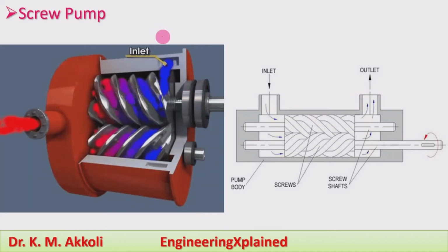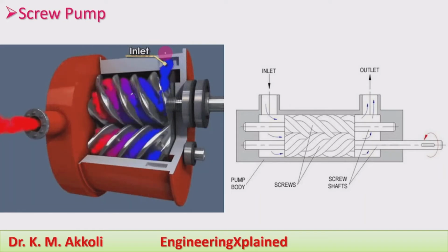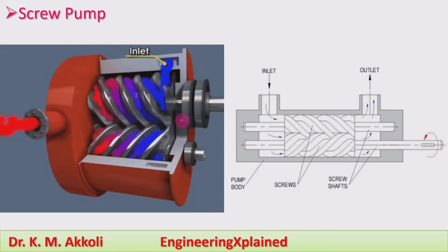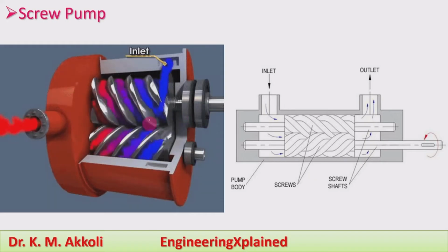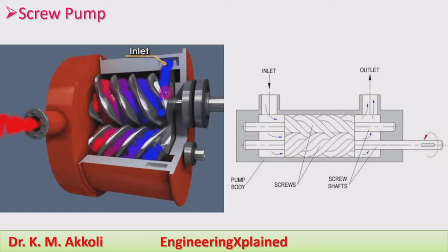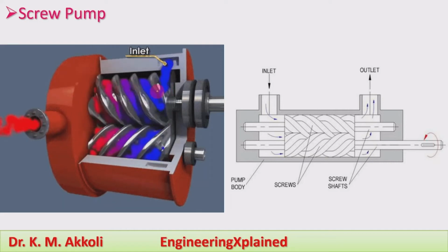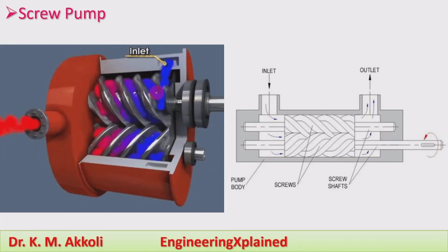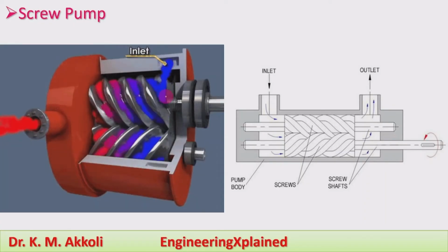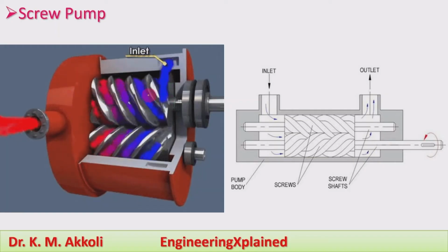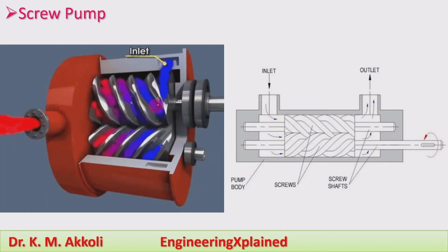The screw pump uses two screws. During the screw movement, the space formed between the two screw flutes is used. During disengagement of the screws, the inlet of the fluid takes place in this space, and during the screw movement the fluid is carried.